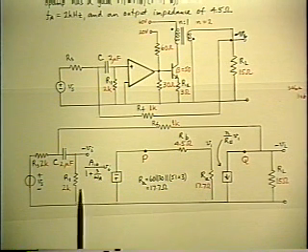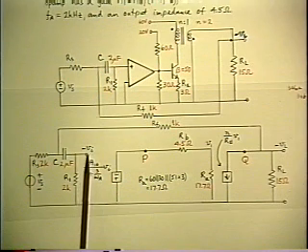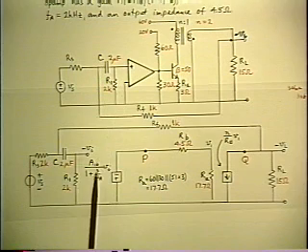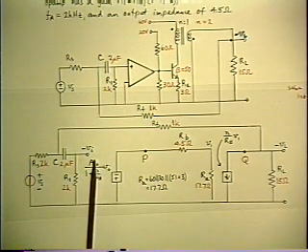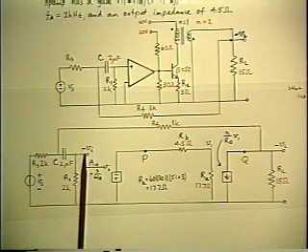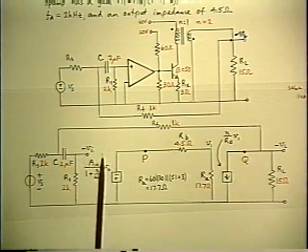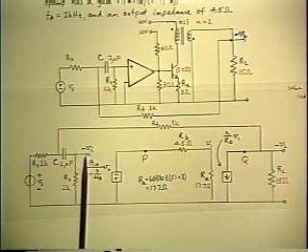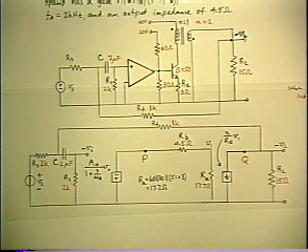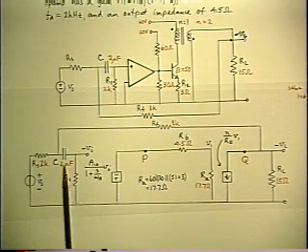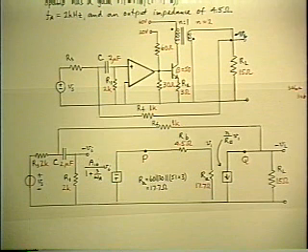Another place to do injection would be right here at VI, voltage injection, because we made the assumption of infinite input impedance to the driver stage. So you could inject a series voltage at this point. And then it would be looking into the infinite impedance. So even though the source impedance isn't zero, the fact that you're looking into an infinite impedance means that you don't upset the loading anyway, because you don't upset the current around that loop, since there isn't any current, because the impedance looking into the op-amp is infinite.